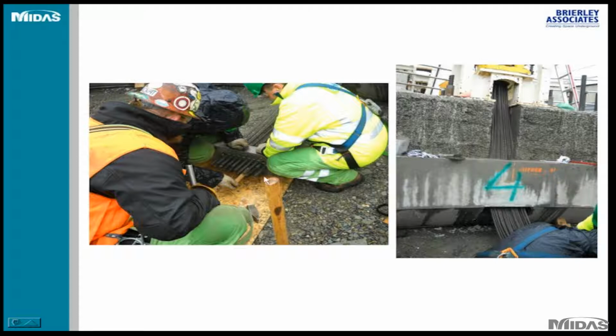On the left photo you can see how they attach the steel strands, or how they are wedged in place into this plate, and this plate will eventually go into this opening. You do the same thing at 3 other locations, so you can suspend this ring and all other rings that will come on top of this ring in place during construction.